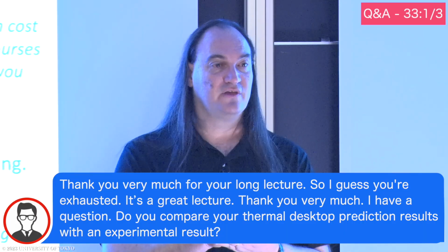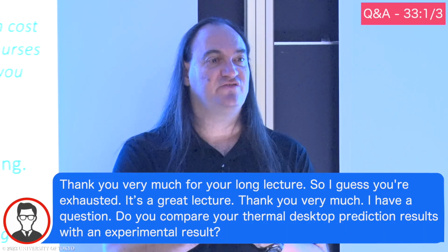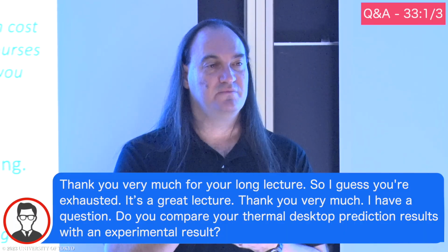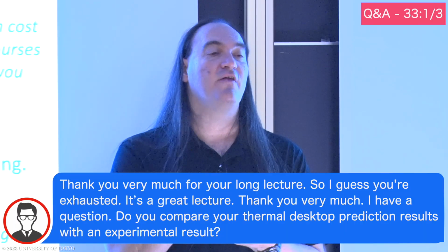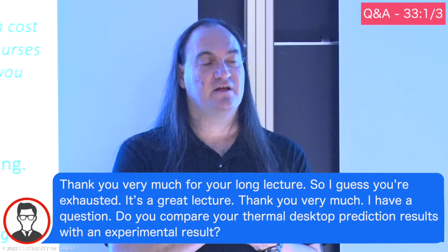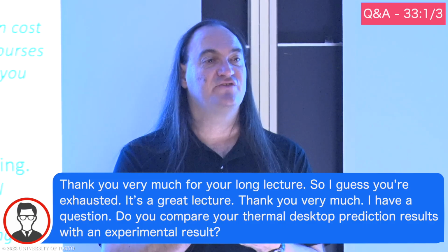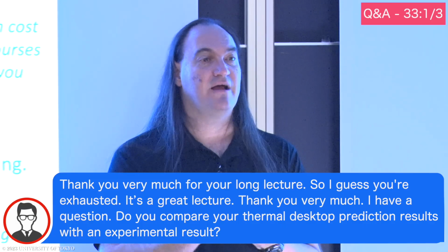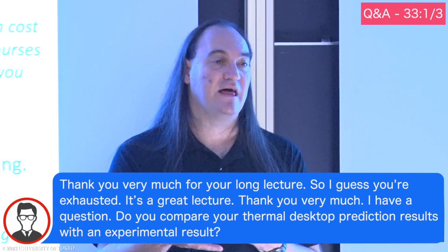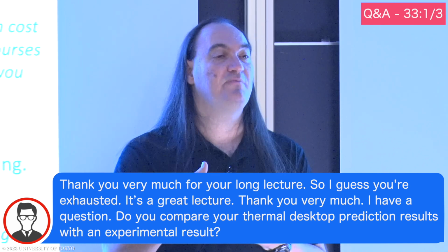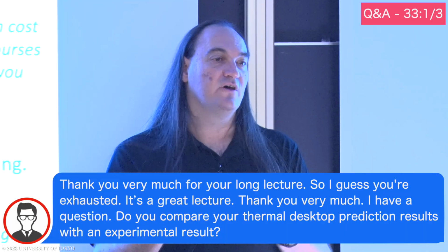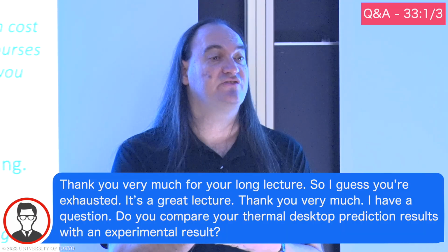It'll be a thermal balance, where we make sure that everything is very stable, so that we can gather the test data. We know our environments. We get all the measured power dissipations. We put all the knowns into our model and see how well it predicts. And if it doesn't predict well, we look and see, well, what areas do we have uncertainty that would get us in the right direction? Maybe the E star that I assumed was too leaky a blanket, and so too much heat came out. Maybe it's better than that. So my test article ran warmer. So my blanket was better than I thought it was. So let me adjust the E star.